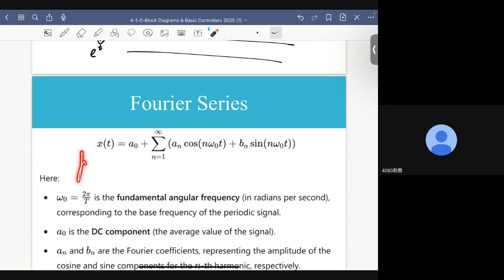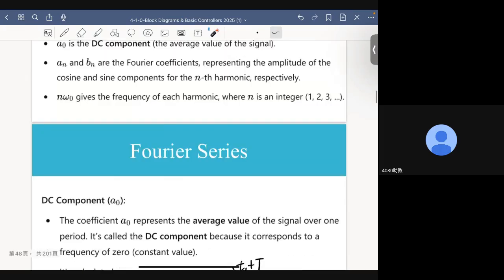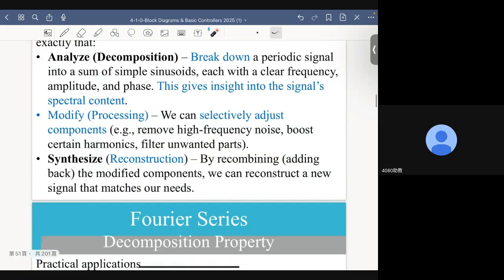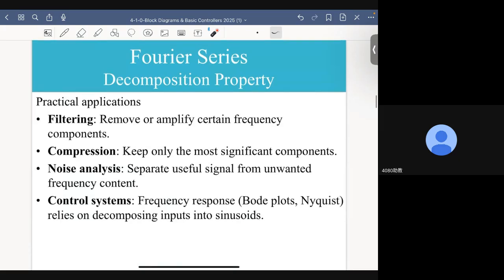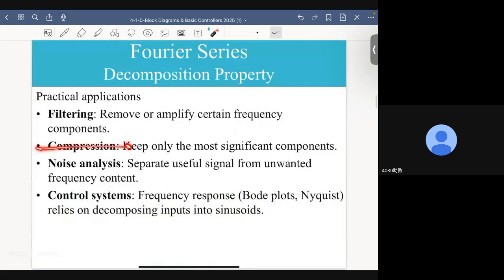So when n is large enough, the magnitudes of these two Fourier coefficients will become negligible, which means if you just simply dismiss them, it will have very, very little impact on the shape of the reconstructed x of t, all right? And then possibly I can therefore compress my signal.